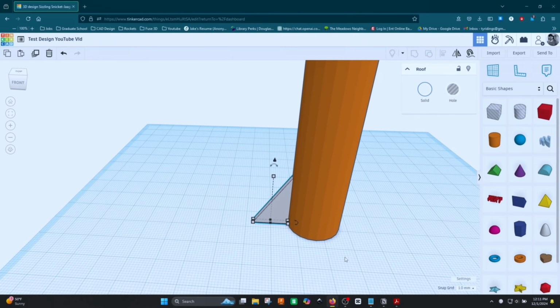And so what I'm going to do now is replicate this all the way around the booster. To do that, I'm going to come up here and duplicate the part. So there's one of two ways to do that. One, clicking on duplicate up here with these little squares, or you can hit Control D. When you do this, you might look at it and be like, nothing happened. Well, it actually just duplicated a part exactly over the top of the part that you duplicated from. So there are currently 2 parts here. And to show that, I'll drag this over so you can see there actually are 2 parts. I'm going to do Control Z to put it back where it was.